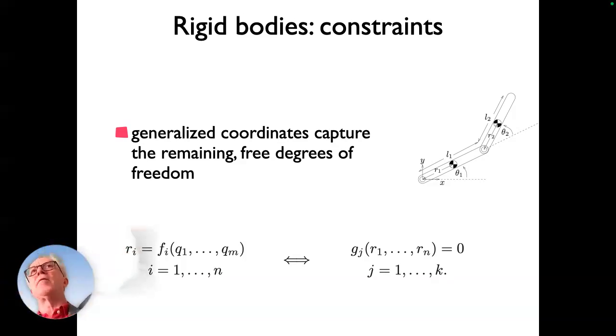The other thing, of course, is that if you have any of these revolute joints, they restrict the degrees of freedom by exerting forces orthogonal to them, right? So for instance, if you have a revolute joint, like this was a robot arm, not a human arm, and I apply some torque in this direction, and it's just one revolute joint, then that's going to be resisted by the mechanics, by the anchoring of the joint, and that's going to make forces. And if the arm is a little bit elastic, it could deform the arm, and that is not usually treated. Ultimately the arm will break, let's say, or would have some vibrations and so on.